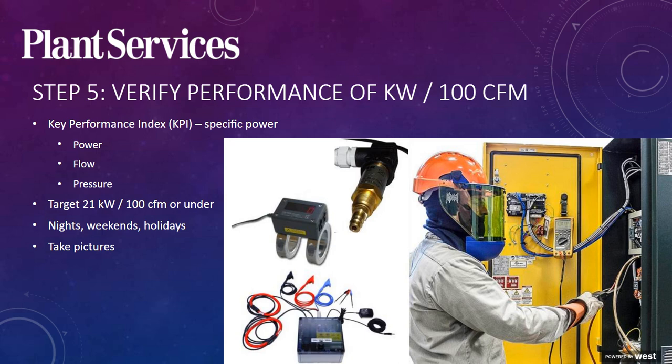All systems can be enhanced, even systems designed using an air assessment or air audit data and that are newly installed. You put in a brand new 55 horsepower or 55 kilowatt VFD, and maybe the pressure settings are at 125, and you can really do 100. So there's various ways to look at that.